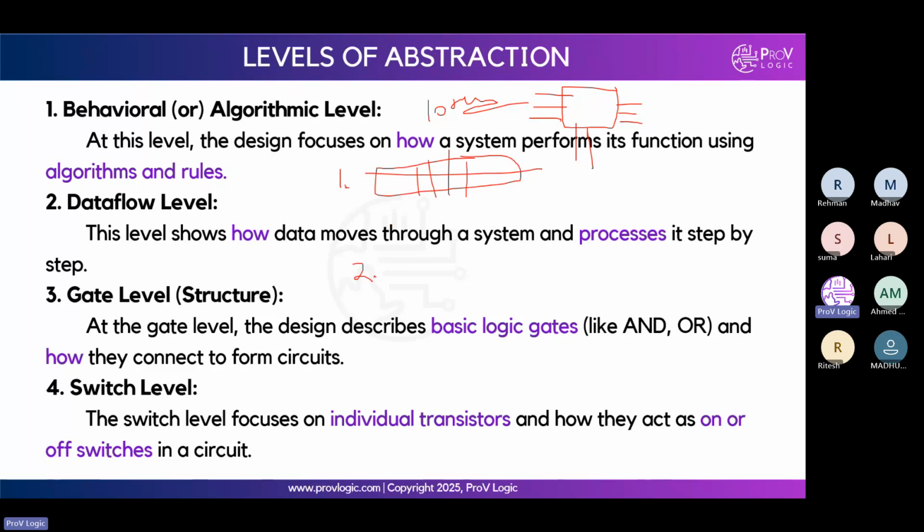You already know POS and SOP format. So we can write the output expression from the outputs of the truth table using Boolean algebra or K-map. You can minimize the expression and get the final expression. That is step 2, getting the expression in digital logic design.